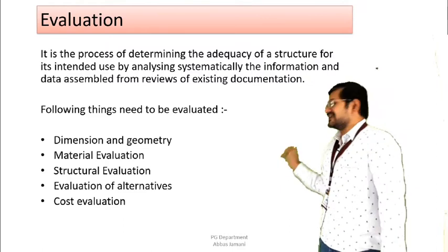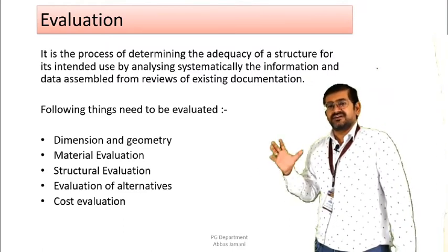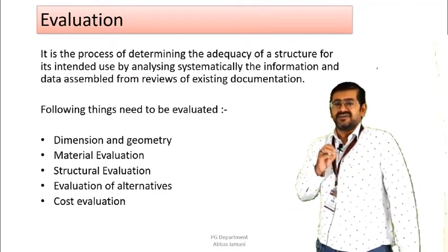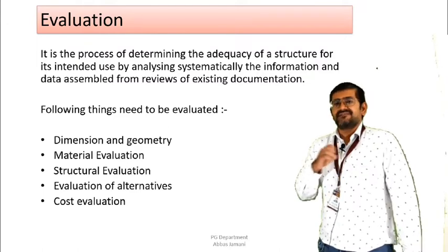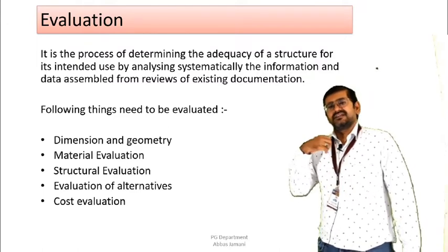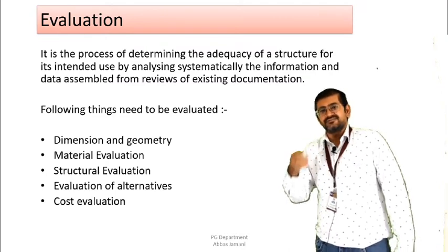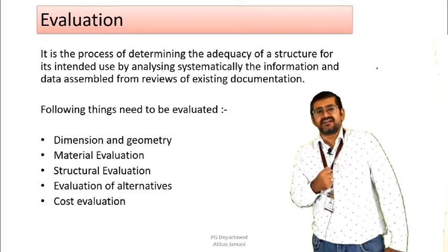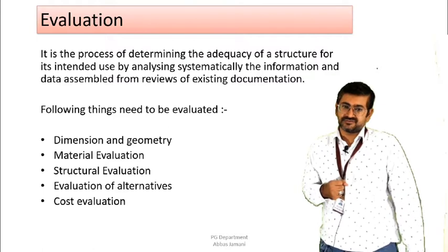Second, you do the material evaluation. That is, whatever the material test or the material data that is available with you, is it the same type of material being observed on the site or not? If any modification is there, if retrofitting material is going to be used, then what is the feasibility of using that material with the existing material? What are the properties of the repair material that will be required? All these things need to be studied under the category of material and geometry.